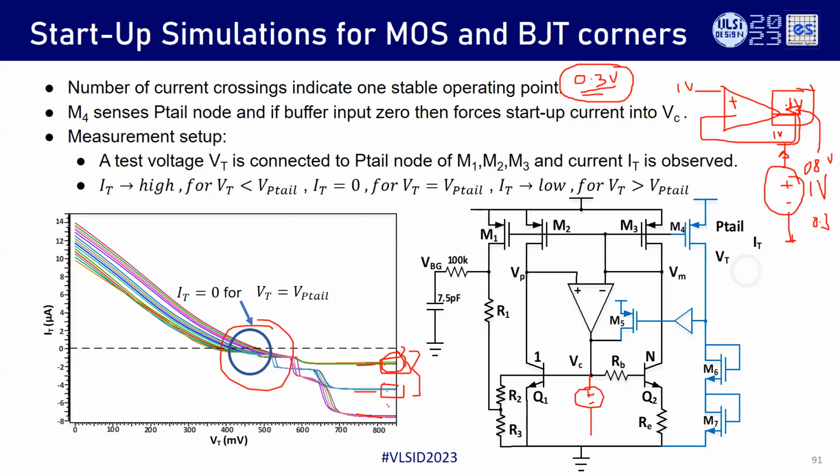This is the reason why we tend to power down every node, so that when you start, it starts from a known voltage. That's why we put every node to ground or wherever a known potential, rather than leaving things floating, so that they start from a known point which we simulated properly. Whereas if you leave them floating, they could start from any voltage which we don't know whether it is a stable point or not. Does that answer your question? Yes. Thank you.